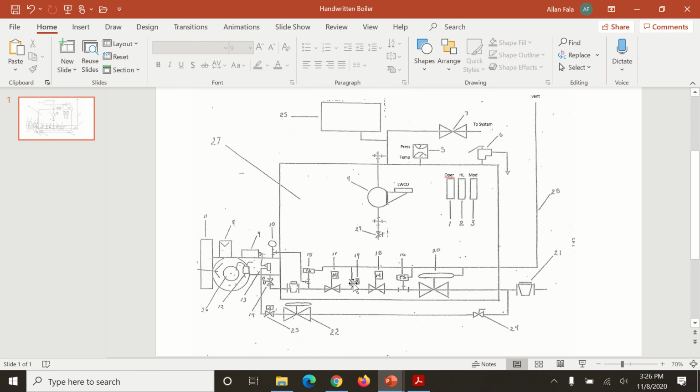That vent valve is open when the other 2 shut to make sure that no gas can build up between these 2. If this valve here was to fail, the number 1 safety valve would fail. Pressure would not make it to the number 2 valve. It would actually go up the vent. But when you look at this being all common venting, that by code is not allowed anymore. This vent off the main gas regulator has to be separated from this vent. If this vent line got plugged here, you could actually get pressure pushing back, which causes the main gas regulator to overpressurize. Not a good idea.